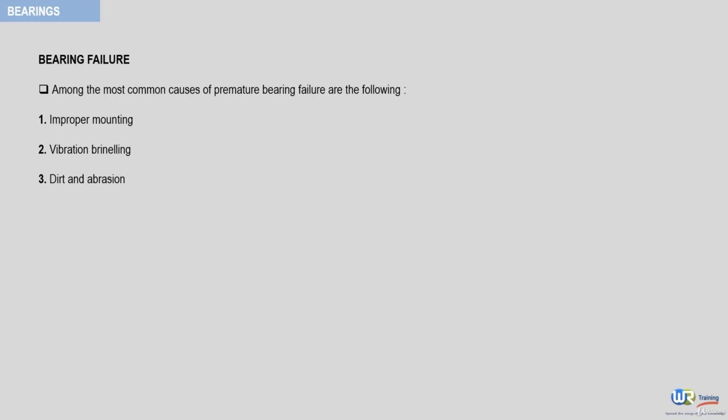Now here are some guidelines to avoid bearing failure due to dirt and abrasion. First, never leave a bearing exposed overnight. If you want to store your bearings, then coat them with clean oil and cover them with clean oil or wax paper.